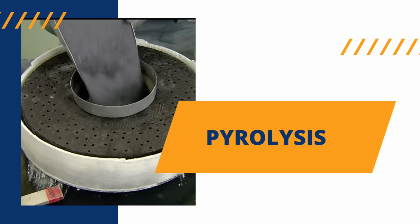That temperature is maintained for many hours, during which the silicon becomes a liquid and pyrolysis occurs. The silicon gradually migrates into the pores of the parent material by capillary action, and the original carbon and phenolic material are transformed into silicon carbide, a hard and highly heat-resistant ceramic substance.